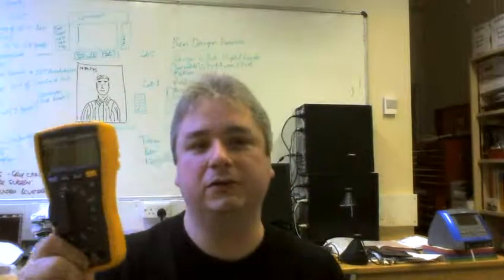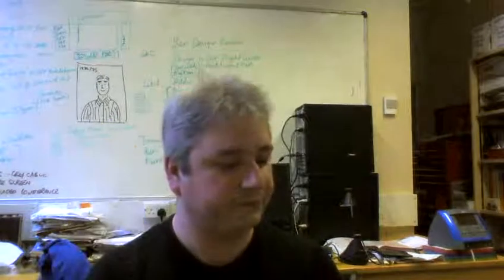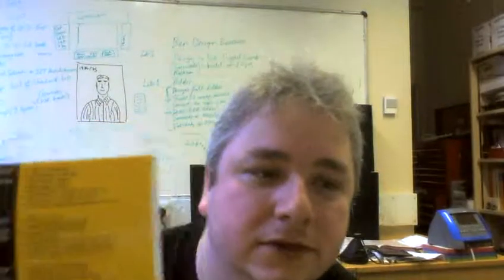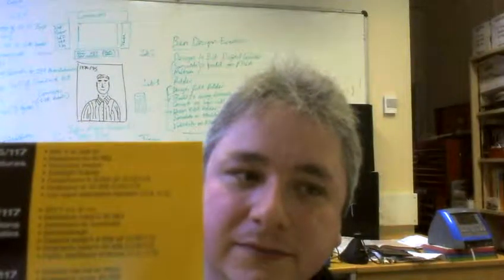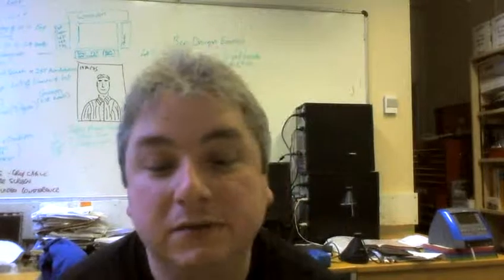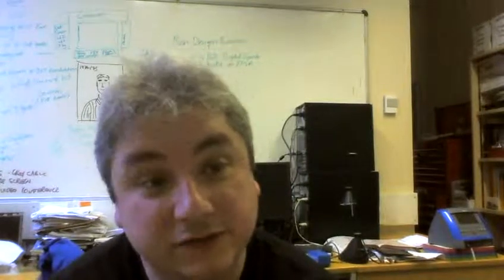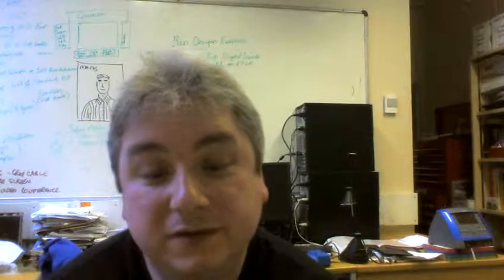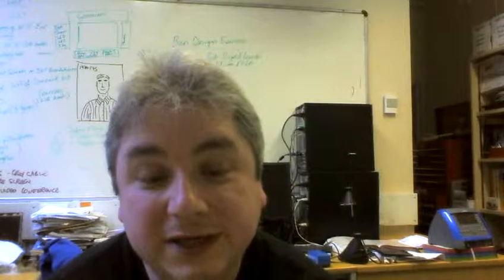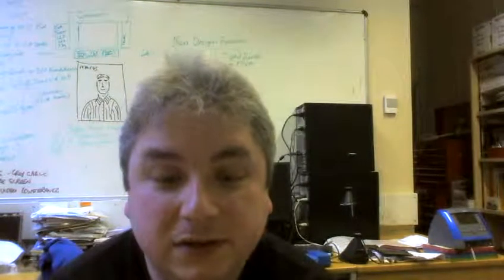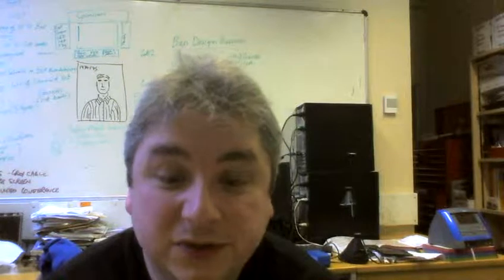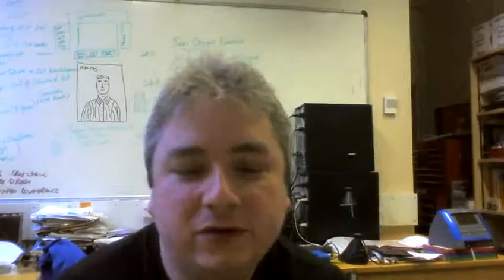So if you go into a shop and you're looking at the back of your multimeter packet, you'll normally see something like this. They give you all the values up here, and it tells you it can measure DC and AC voltages up to 600 volts. Yeah, okay. Resistance measurements of 40 mega ohms, continuity, capacitance measurements. It does low impedance measurements on a different model. It's the 115, but it actually specifies that for the 114, 117. So you have to be careful which ones you're reading.